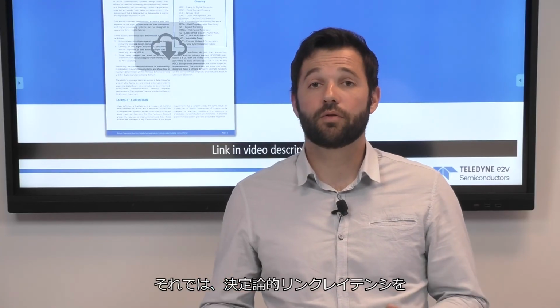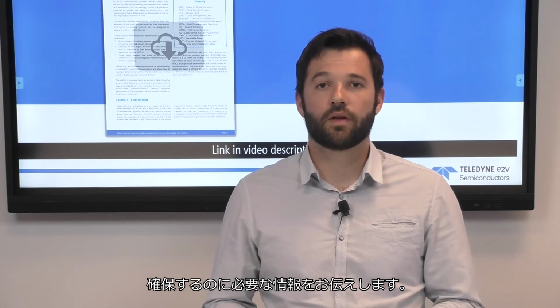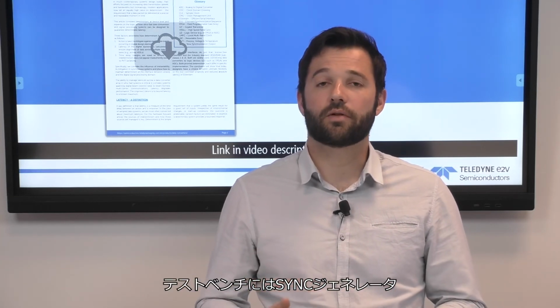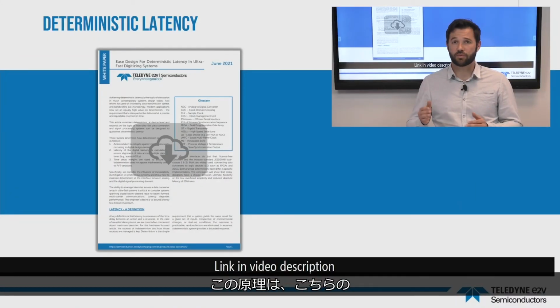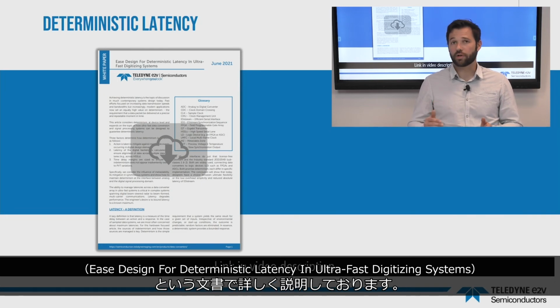Now, I will give you the information you need to ensure a deterministic link latency. It means a constant total link latency over multiple power-ups and resets. The test bench includes the sync generator plus the sync counter. You can use these modules to release sample data at a deterministic time. The principle is detailed in this white paper, designed for deterministic latency in ultra-fast digitizing systems.